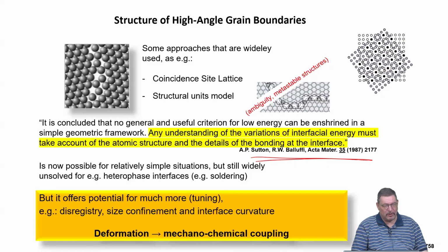But I think it gives opportunity also to think of tuning the boundary structure by going beyond what we today understand as grain boundary engineering. For maybe you who have not yet attended the higher classes, grain boundary engineering was investigated by a Japanese colleague called Watanabe, and he basically described making a better material by choosing a high fraction of these special highly symmetric boundaries, so CSL boundaries with a low sigma value, mostly a lot of sigma 3 and sigma 3 derivatives like sigma 9, sigma 27.